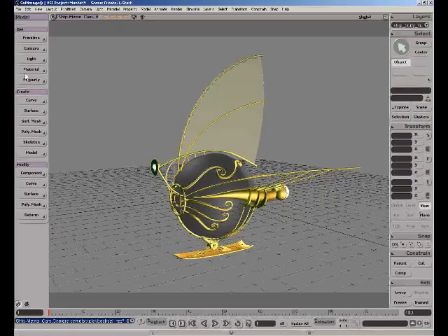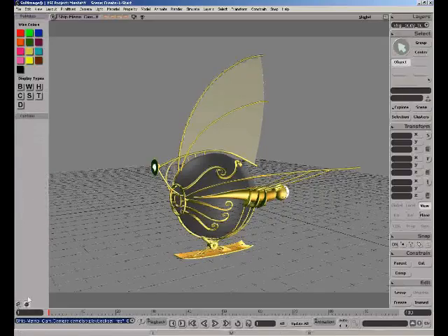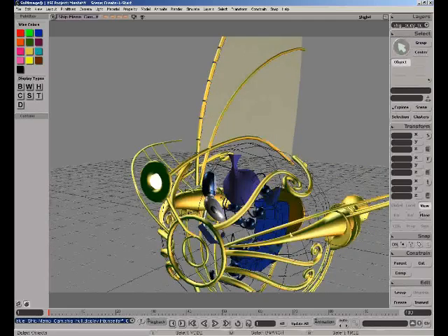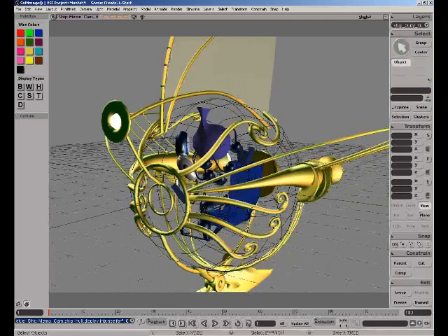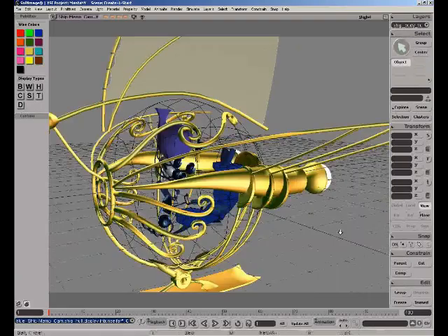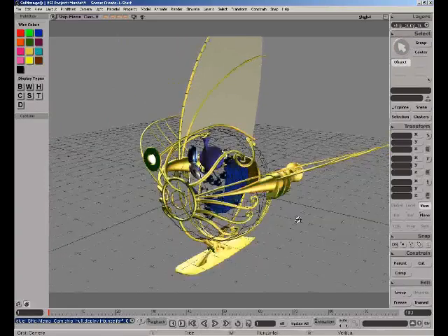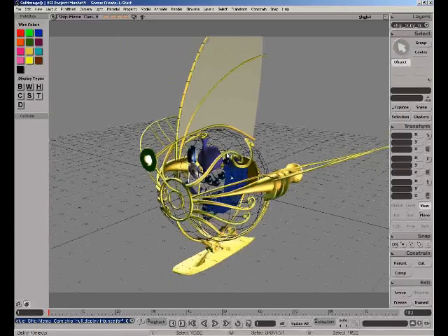If we go into a mixed view, we can click on this little icon here, and we have these little options here, these little letters, and this allows us to do the following. If I click on the W icon, this brings me into wireframe mode. I can click here, and now you can see that just that object is in wireframe view. So this is called a mixed viewing mode, and it just allows you to really custom tailor how you want your scene to look inside of your OpenGL. Of course, when you render this, it'll all render solid again. But by doing that, you can see we're now looking at the inside of Manta's spaceship.